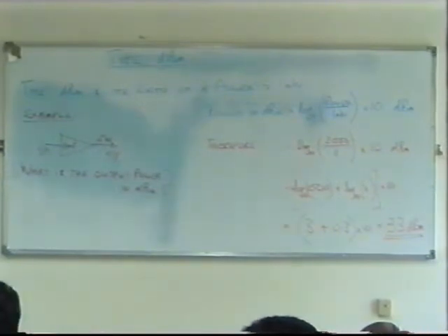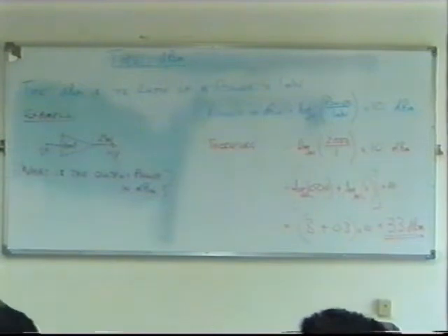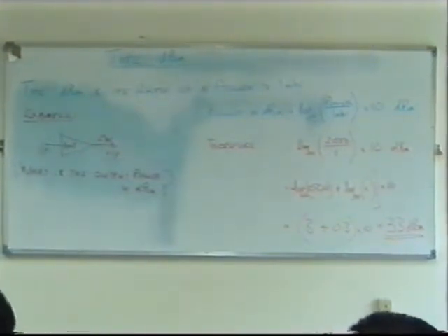let's say you connect a modem to a telephone line. Now, the PTT will say, according to their network, whatever you do, don't put more than 30 dBm. Actually, that's a big figure, but let's choose that as an example. Don't put more than 30 dBm power out onto the telephone line. Okay? That's maximum power. It is a measurement of power.